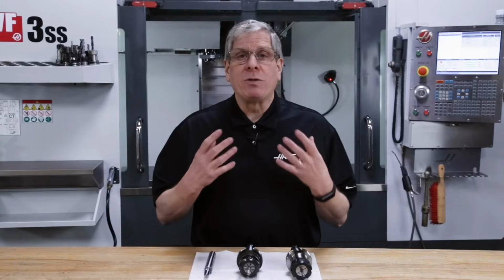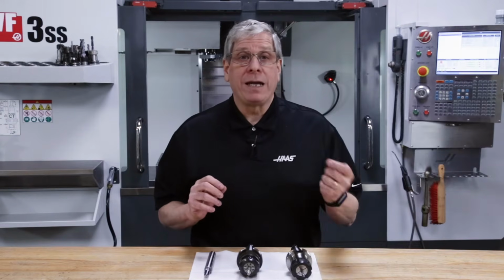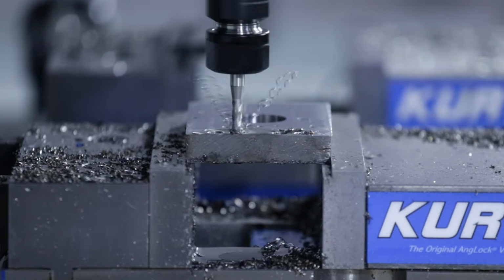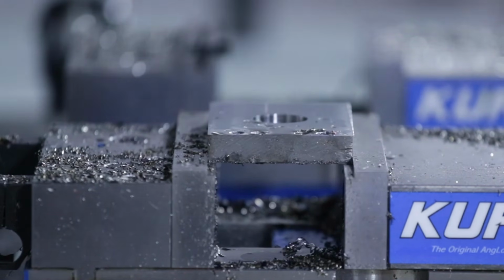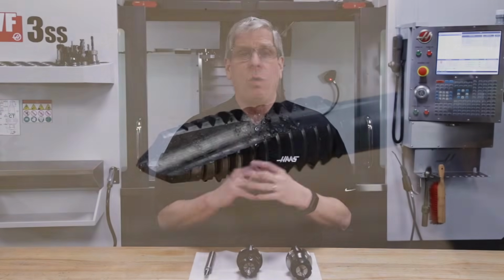Here's a tip about cutting taps. If the flutes spiral around the tap like a twist drill, the chips cut by the tap will come out of the top of the hole. You should use this type of tap when the hole you're tapping does not go all the way through the material. These are called blind holes.